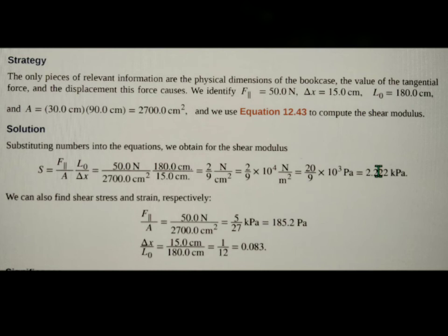which is 0.083. So, if the person in this example gave the shelf a healthy push, it might happen that the induced shear would collapse it to a pile of rubbish. Much the same shear mechanism is responsible for failures of earth-filled dams and levees, and in general for landslides.